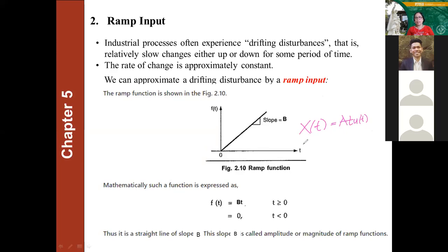Now, if you take its Laplace transform, you need to go back to the basics. That would be A over s squared. Why do we have this? Because we took the Laplace transform of t, which is 1 over s squared. If you're interested in y of t in this case, it's the same thing. You have to go back to the transfer function, which is (1/tau) over (s plus 1/tau). And then your corresponding Y of s would be...